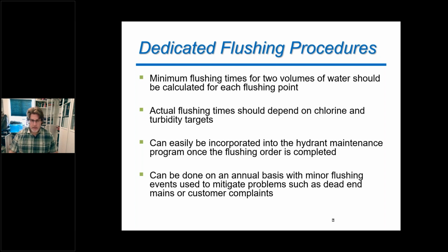There are always limitations on this. Once again, what is your drainage like, but also, what is the capacity of your water system? And that's looking at your reservoir volume, right? So you might say, hey, I've been flushing for 15 minutes and I'm getting a low reservoir alarm. I need to shut this down, but I'm still not getting good chlorine residual. My turbidity is still not where I want it to be, but I just don't have the water anymore to continue this flush. Again, that's good record keeping to make. Shut down your flush, go back to your plan. Try to bring in other people. Talk to your drinking water officer, any engineers that you have working on the system. Reach out to the small water users group here on the website, and try to ask, hey, this is my problem. What can I look at here to maybe do this more effectively?